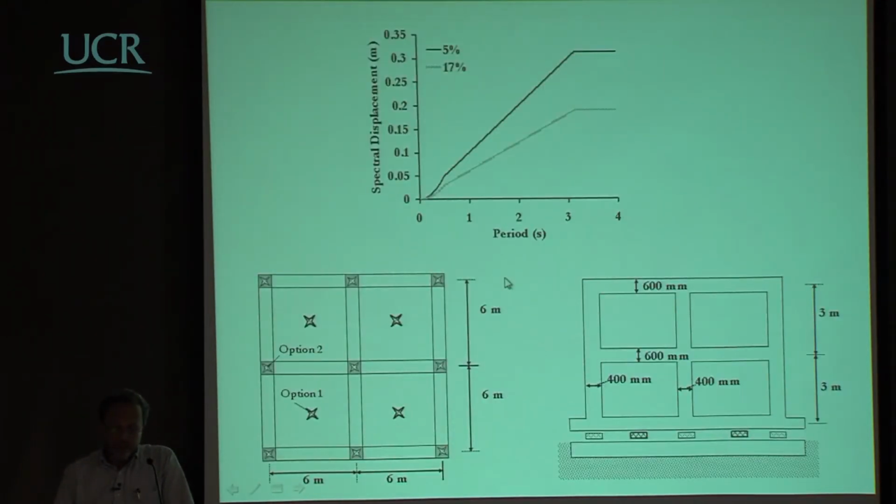Well, the problem could be a technological problem. Because if you have a structure like this, you may say, okay, I'd like to put 9 isolators below each one of the columns. But don't forget that if you use, for example, rubber bearings, there is a correlation between the vertical action and the horizontal stiffness of the bearings.